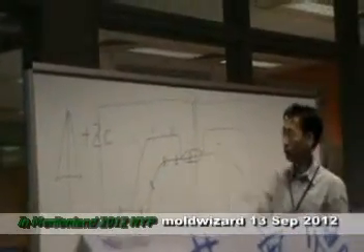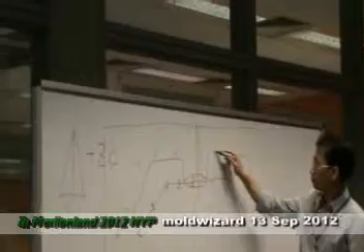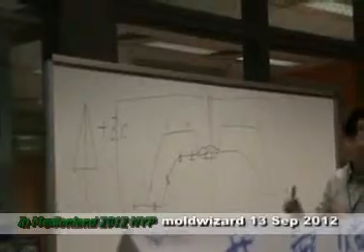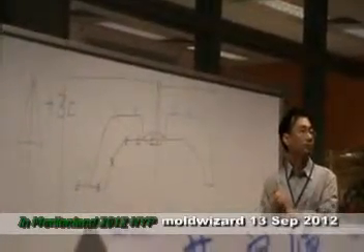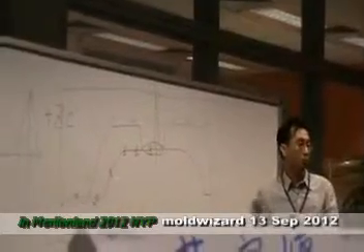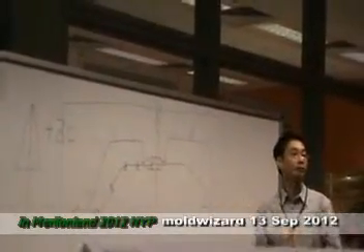So if we have two, we hope it's just well balanced, so we can have a longer tool life. And if you still worry about this, it's okay to add some locking system in your mold base, so we can protect our mold base and prolong your tool life. That is some consideration.